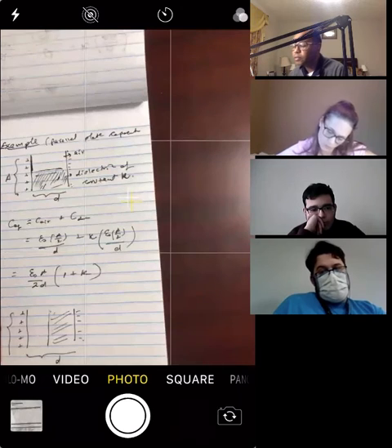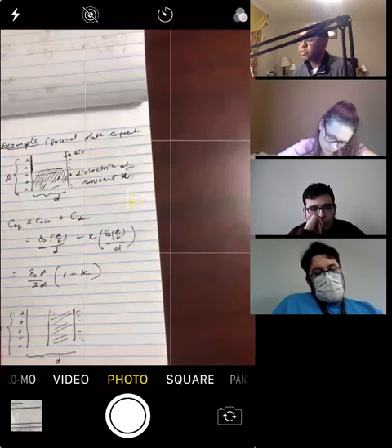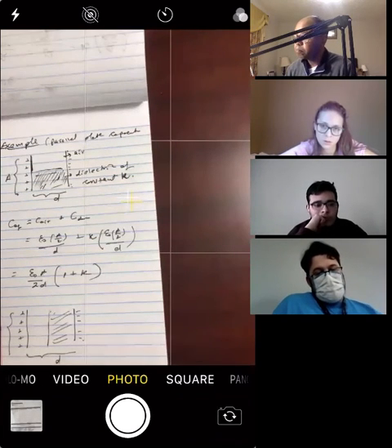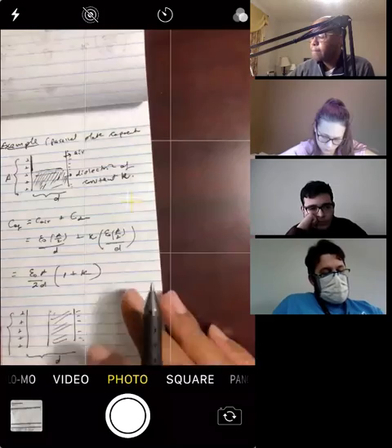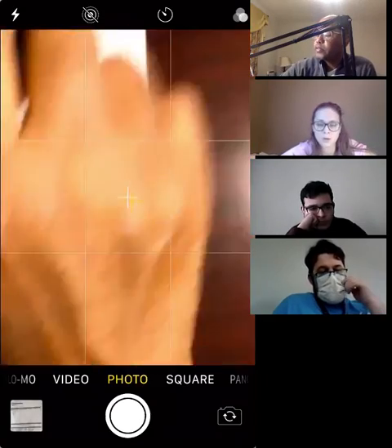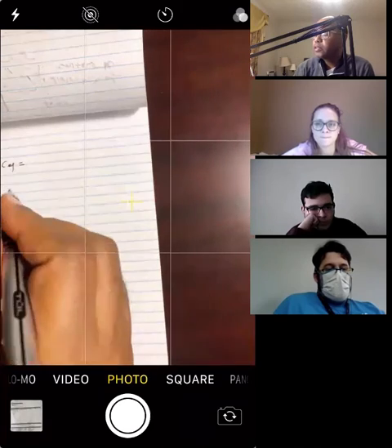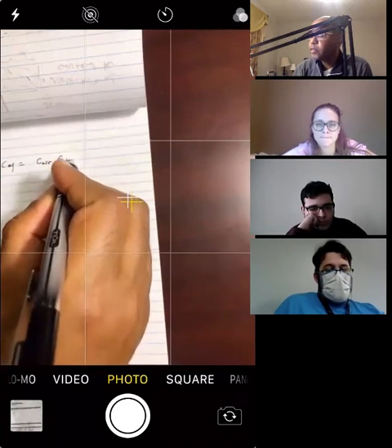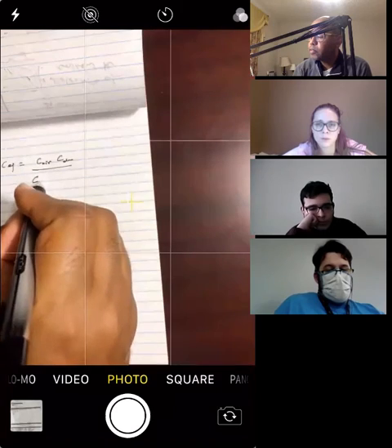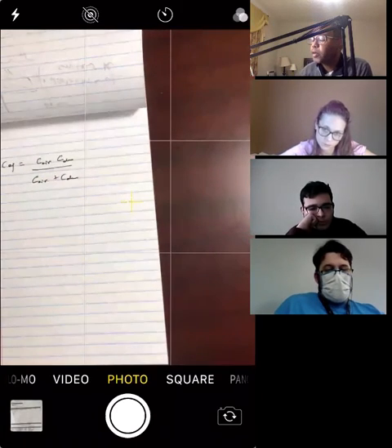Now, do you think these two capacitors are in series or in parallel? Series. These are in series. You see plus, minus, plus. So we're going to use product over sum to add them. So the equivalent capacitance in this case is the capacitance of the air one times the dielectric one, divided by the sum, C air plus C dielectric. That's how we're going to add them.